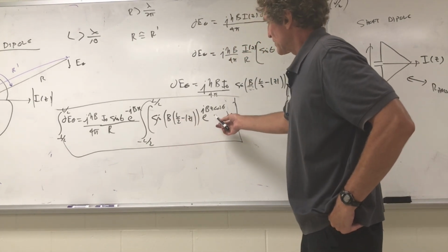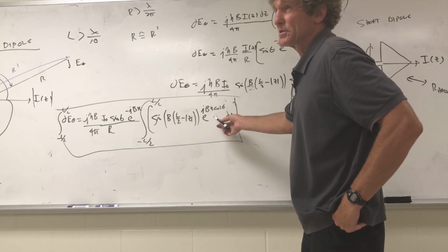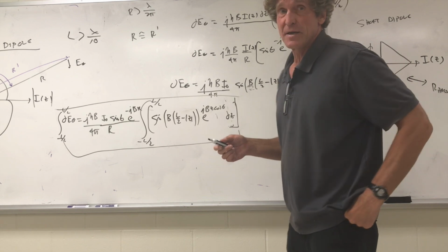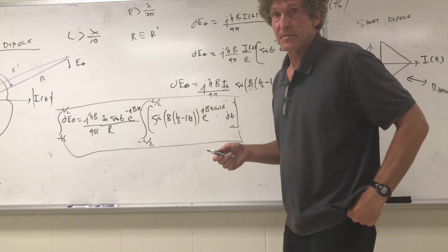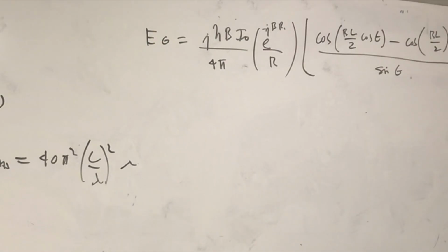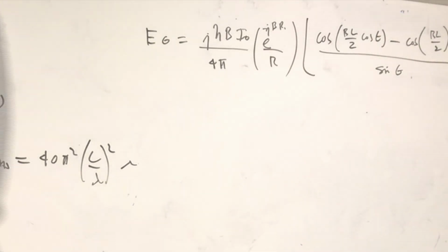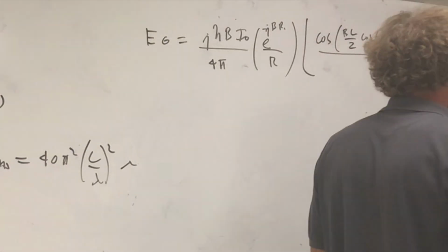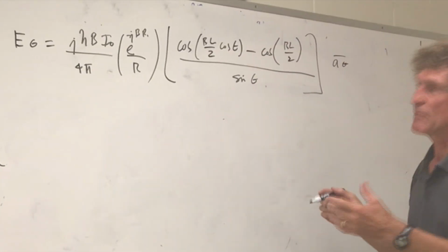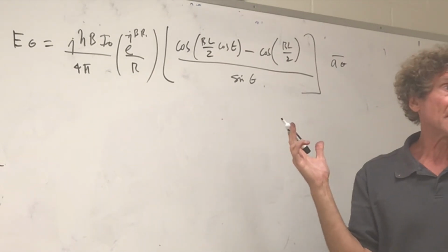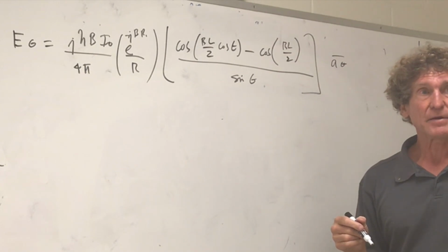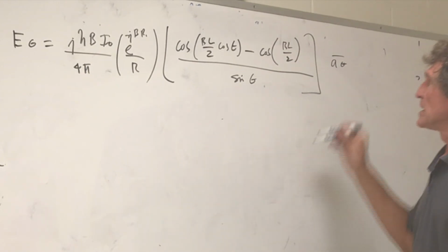And we're going to say, this is an integration in the back of the book, but this is a u dv integration, I believe, or v du type thing. And you got to bring the sine theta. But at the end of the day, here's what's going to happen. He has the H field for his. This is the E field for me. If you look at this, this is kind of important. Whitmore's book has the H field. How would you get the H field magnitude if that's the E field class? Divide by eta and reorient and put it in the a phi direction. Everybody agree with this? Now, here's my point.